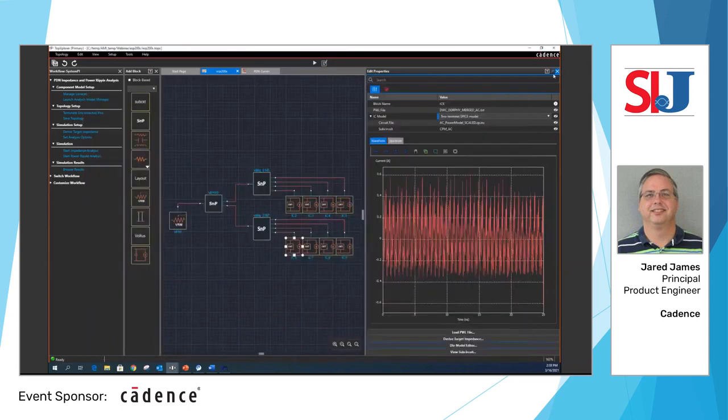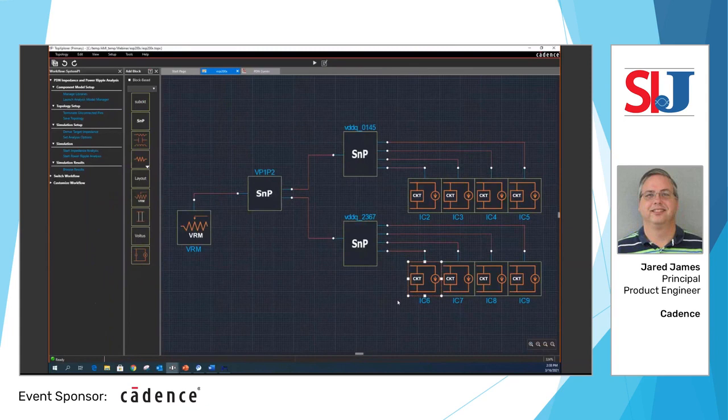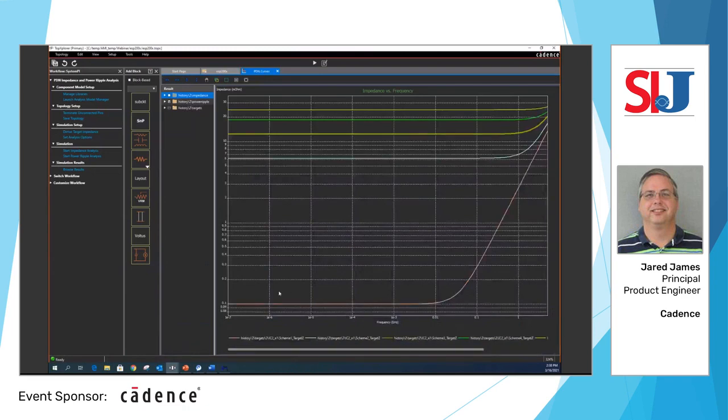Once you have your IC model defined, we can generate what we call a target impedance. In the background, we're using some other Sigrity X tools to give us various target impedances that we can feed back to our board and package designers. After that is run, this is one of the example outputs you'll get. Here we have multiple different solutions that will meet the power ripple spec we were given along with the PWL and the IC. Once these curves are generated, as I mentioned earlier, you can feed these back to your design teams to discuss how to have the targets met.